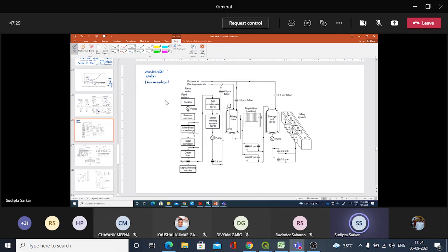You see that wastewater. I think probably you have heard about or you know about the activated sludge process. Okay, so in activated sludge process, what we do, we try to grow our bacteria right here, and then we try to settle the bacteria and then recycle our bacteria back into the process, and a part of the bacteria is removed here, and we get the treated water. So from right here. Okay.